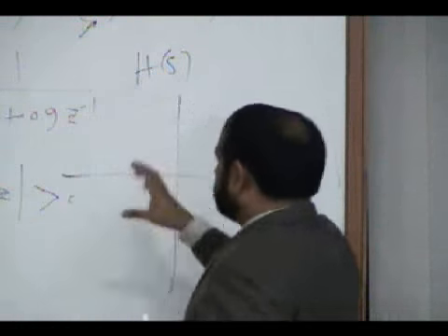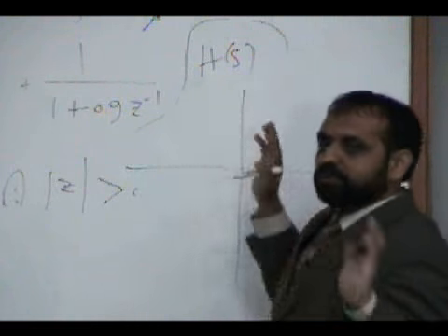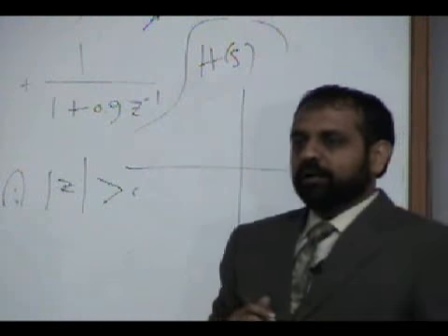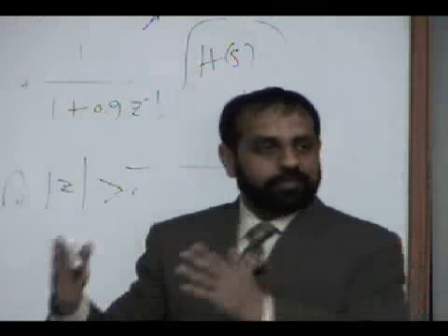So you usually design the control system in h of s. All the control systems are designed in h of s. Now you cannot implement h of s using a computer program, so you need to convert it into the z domain.